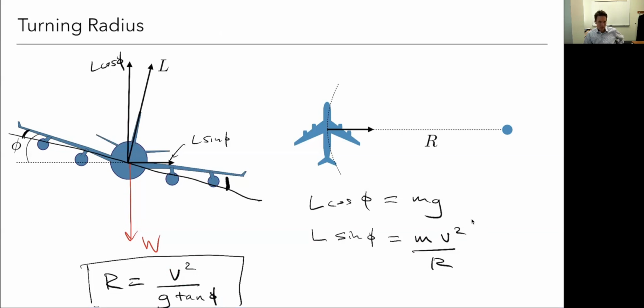The other is I can bank further, right, if I can get to a bigger angle. And if this is a passenger carrying aircraft, of course, there's going to be limits on that. We're not going to be very comfortable if I'm pulling big bank angles. But if I don't have passengers, I may be able to get away with more there. There's also limits there in terms of g forces, potentially, although we usually won't get that high.